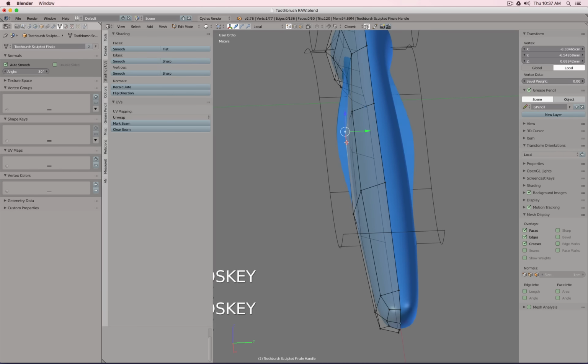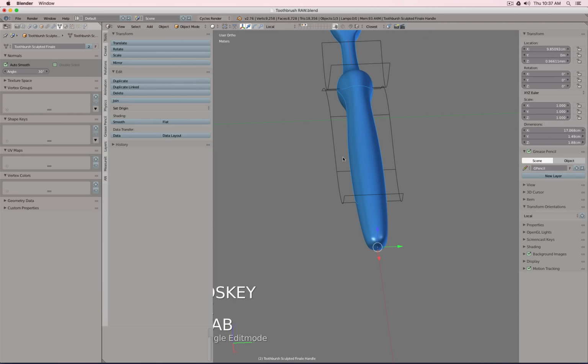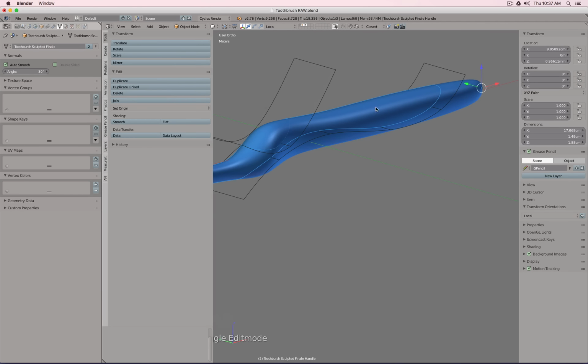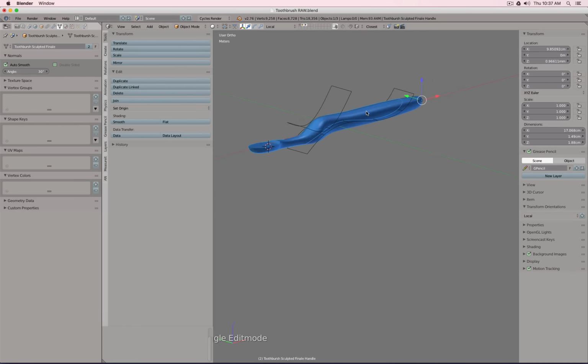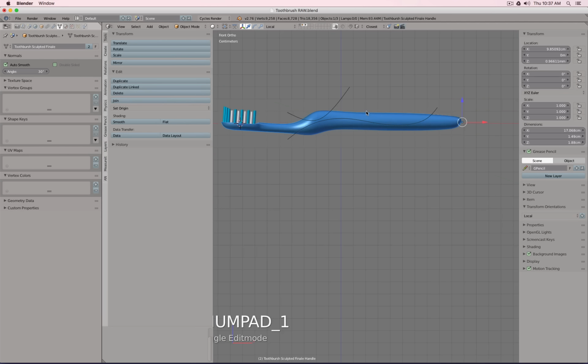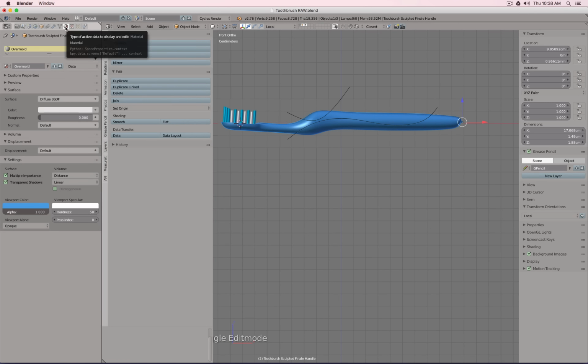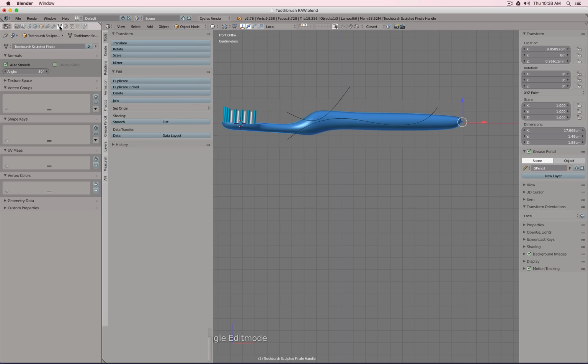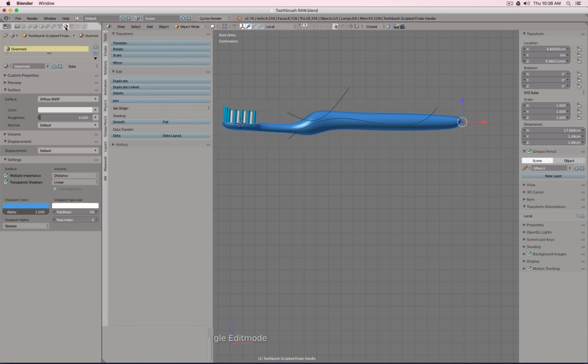Because in Fusion, we end up with two objects, and in Blender here, I work with two objects. But how do I get the materials different? Currently, this is really difficult to read. So let's go to the materials tab, and you see this one is linked to data. So what's data? Well, data is the mesh. So the mesh gets that color. That's not really what I want.